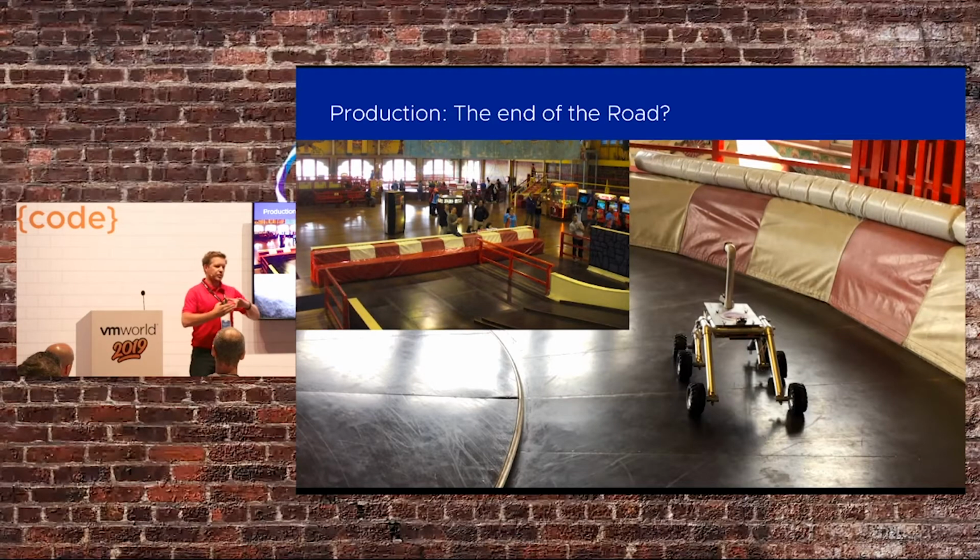When the rover was trying to work out if it needed to do something for an object, it took so long for the response to come back, and it was waiting because our code was running in series instead of parallel. So we were waiting for things, and the rover was really jarring around instead of moving smoothly. We had to change a lot of those settings on the fly. We also had a couple of problems with noise. Because it's ultrasonic sensors, when you get a lot of noise in the environment, it can really affect it. It just became a lot less reliable.